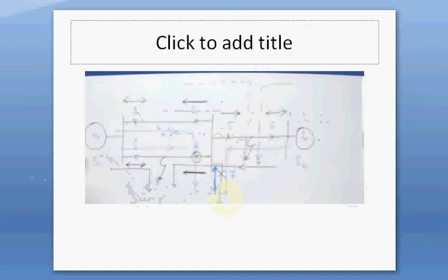One thing also very commonly asked in the GATE exam is, if the fault occurs in this region, what are the backup relays for relay 4? Now how can we calculate the backup relays for relay 4? Now see, in this case, if the fault occurs between 3 and 4, then 3 and 4 both have to react immediately so as to eliminate this line from the healthy system, so as to eliminate this fault.